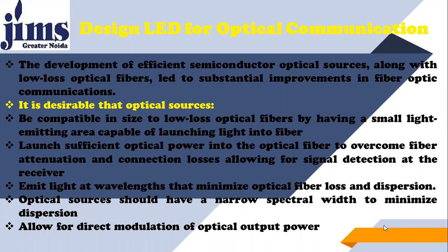So by using the best optical source and the best optical fiber in the sense of low loss, we can improve the optical communication system. So what do we need from optical sources, and what do we desire? Number one, be compatible in size to low loss optical fiber, meaning the size of the optical source should be compatible with the size of low loss optical fiber by having a small light emitting area